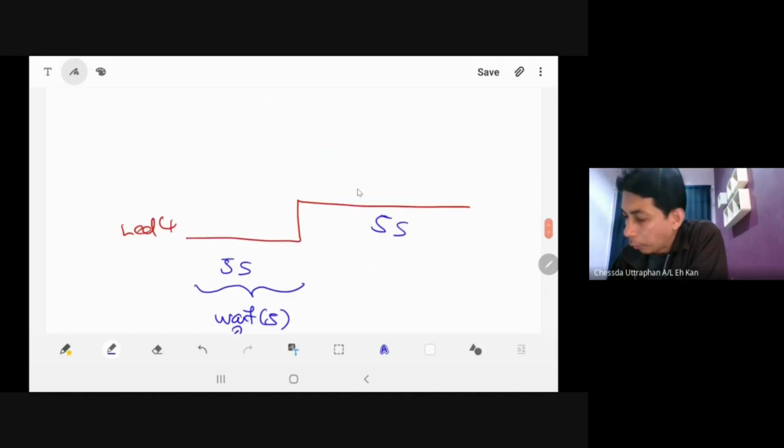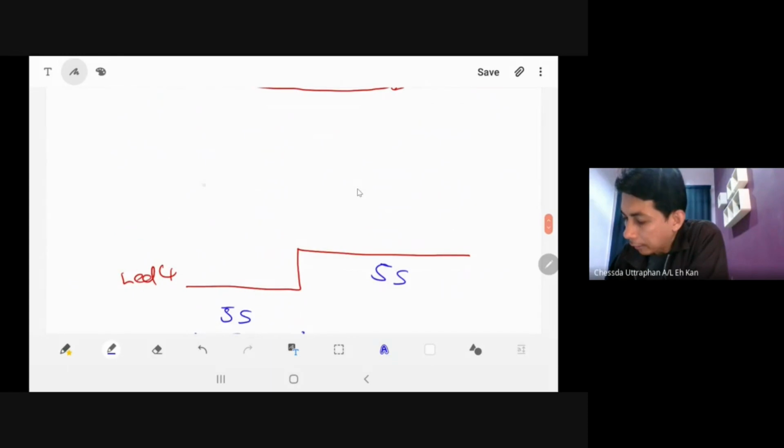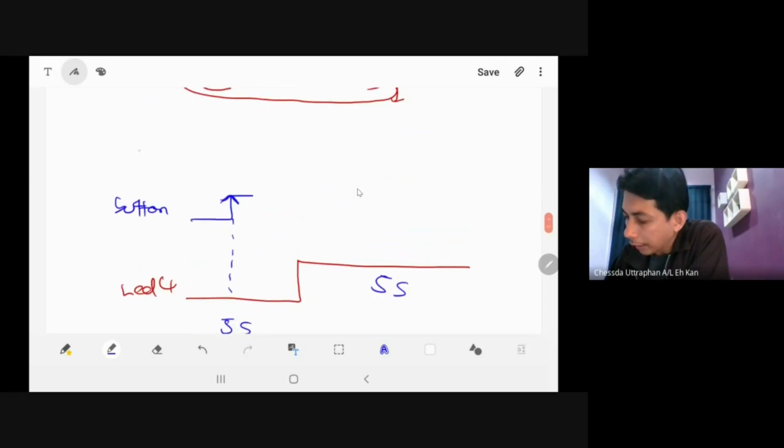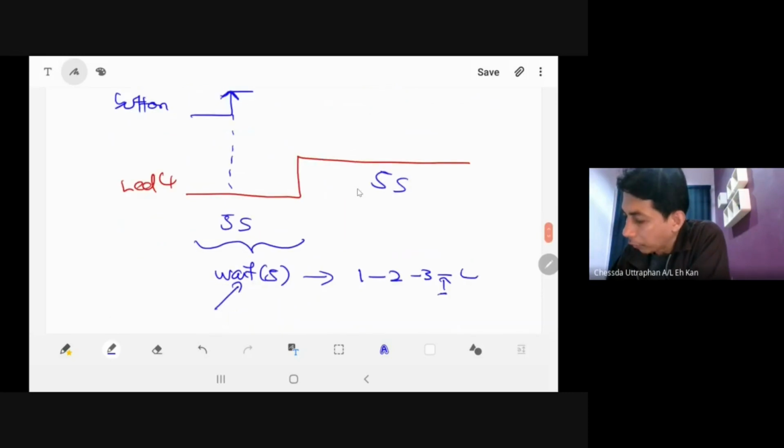But when you use interrupt, this is the button, and here you interrupt. So for example, the microcontroller counts from 1 to 2, 3, and here you interrupt. The microcontroller actually will stop counting very fast, go to turn on the LED. This is LED 1 from 0 to 1. Turn on very fast, and go back to the counting, number 4, number 5.